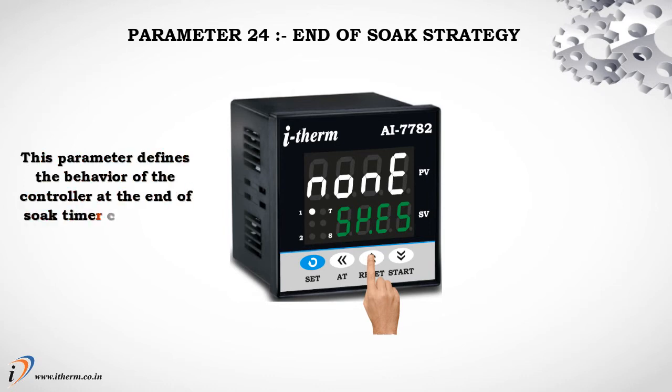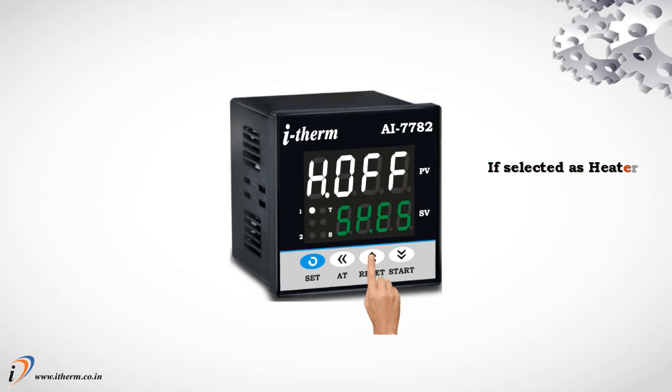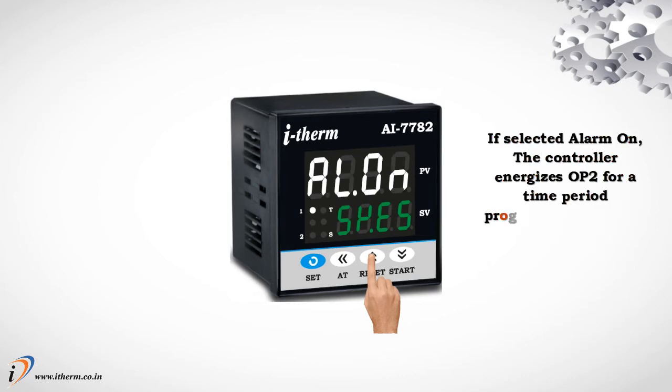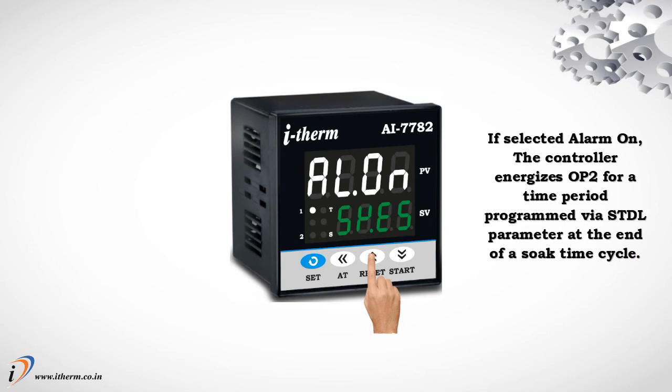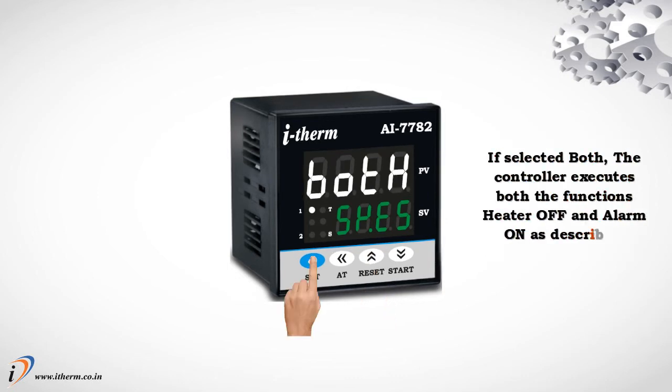This parameter defines the behavior of the controller at the end of soak timer cycle. User has four options. If selected as none, the controller maintains process value at set point indefinitely irrespective of start or at the end of a soak timer. If selected as heater off, the controller de-energizes output 1 as soon as the soak time is over. If selected alarm on, the controller energizes output 2 for a time period programmed via soak time delay parameter at the end of a soak time cycle. If selected both, the controller executes both the functions heater off and alarm on as described.